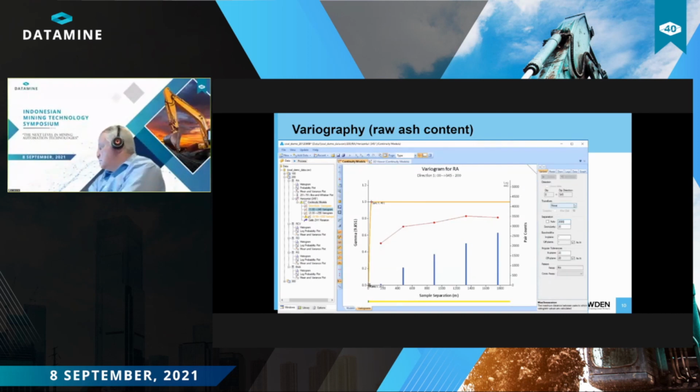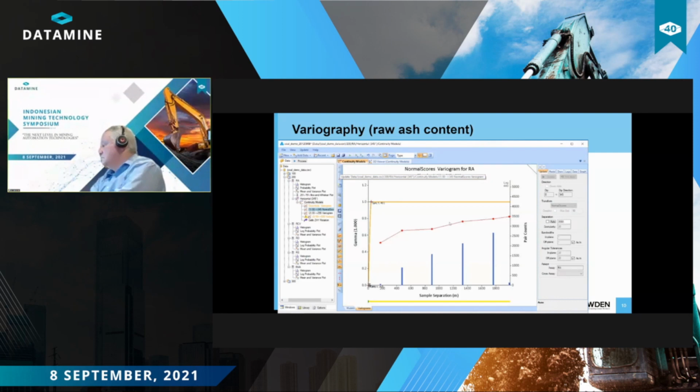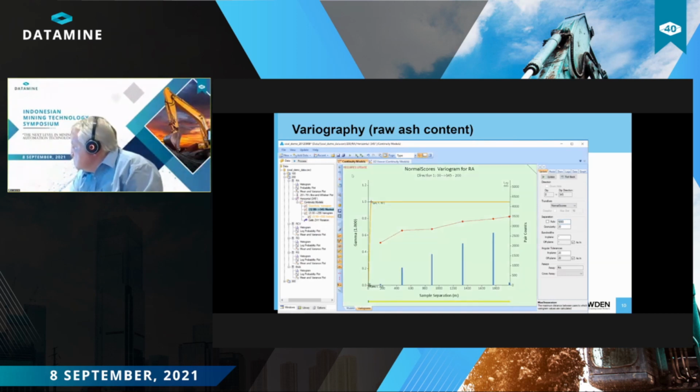Next, we're going to set the transform to a normal scores transform. The reason for this is that in the subsequent conditional simulation exercise, we're going to need to use variograms that have been developed in Gaussian space. Also, we're going to open up the total separation here to about 5,000 meters so that we can look further out.